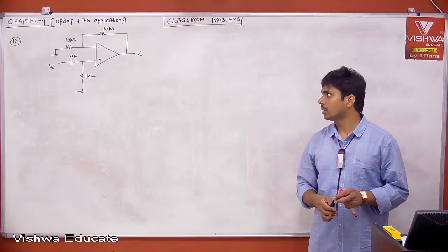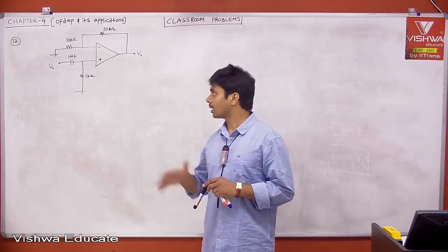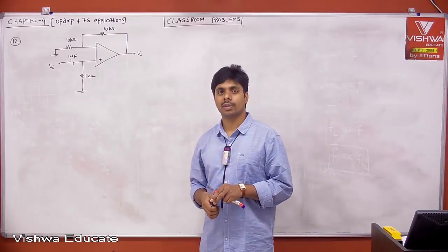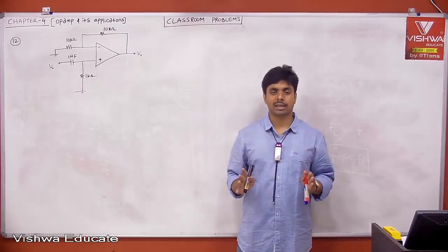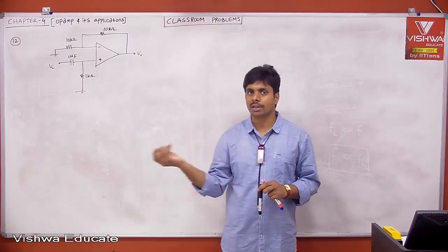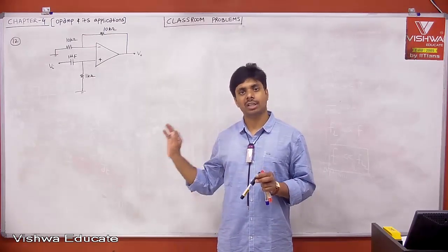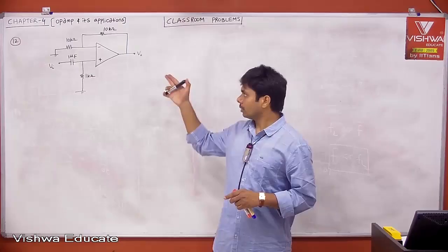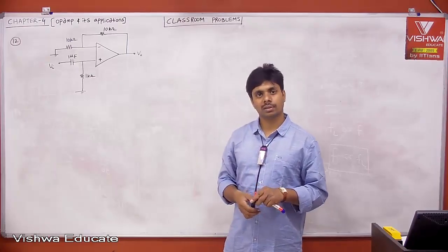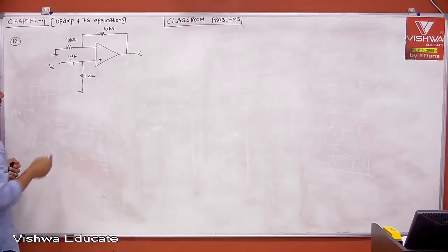Okay, that is fine. Now, will you treat this as a filter problem like an RC circuit or an op amp problem? See, the blind technique: treat it as an op amp problem. If you know a little bit qualitatively about the circuit, that is fine. But if you want to get the answer finally, treat it as an op amp problem. Negative feedback or positive feedback? Negative feedback, right? Then virtual current concept is valid?